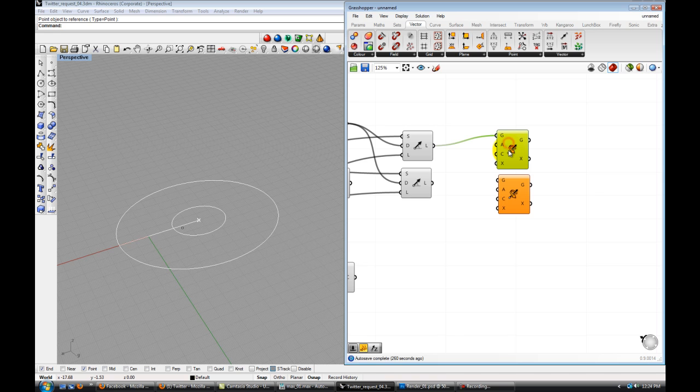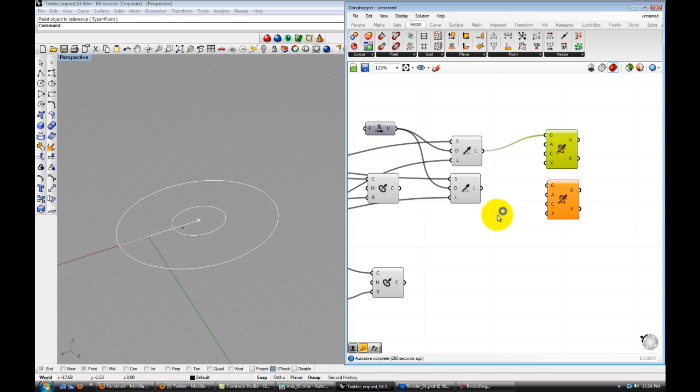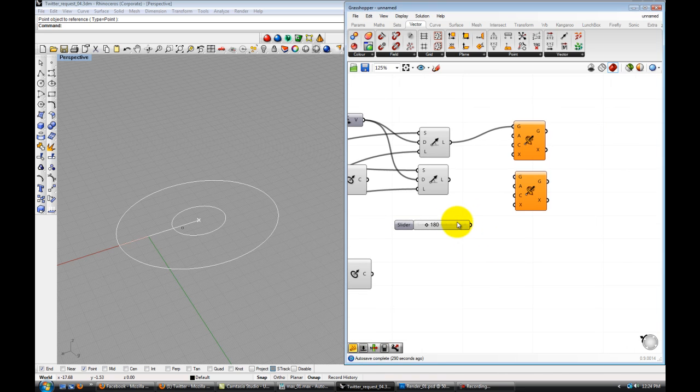So you want to rotate that line, and it would be easy to just punch in a number. However, it would not work, since all the numbers for the rotation angle, if we just type in 180, will be in radians, which is not what we want.